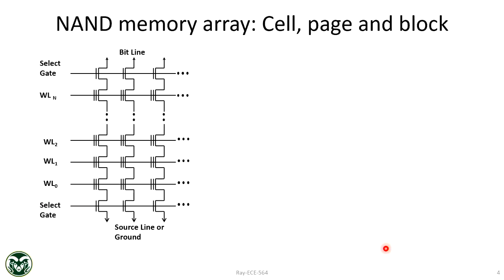Okay, so if you look inside a block at how the bits are arranged, this is the cartoon of a block. These are flash memory cells. We put 3 lines here just to show there is a floating gate. It's a floating gate cell, so you store information on the gate stack in the form of charge. But this is not a floating gate, this is the select gate. So this selects which block you want to select. The top and bottom are the select gates. In between you have memory cells.